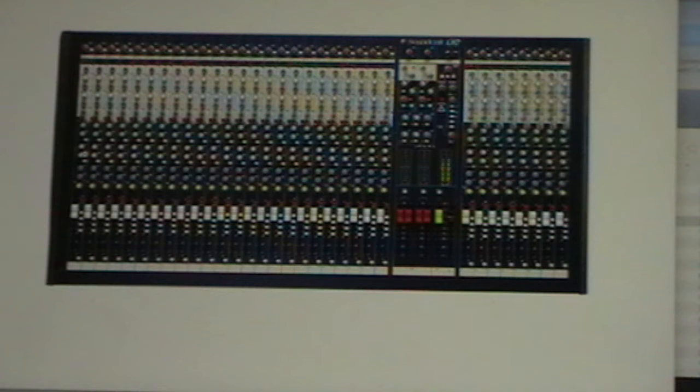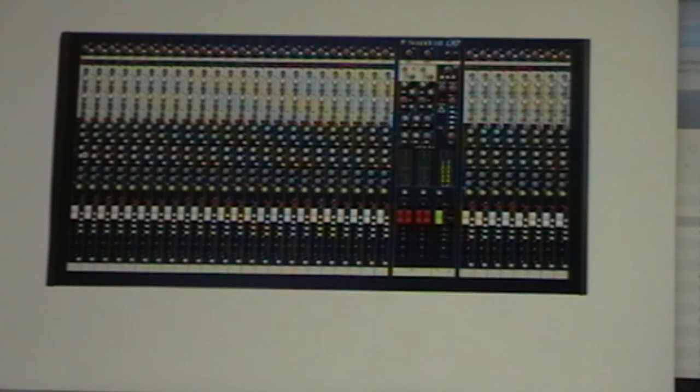So things like delays or reverbs are normally employed on the recordings of instruments like vocals, acoustic guitars and tambourines. Now you've got your pre and post fader sections. Your pre-fader lets your audio signals be sent to the auxiliary channel when the channel fader is not employed.